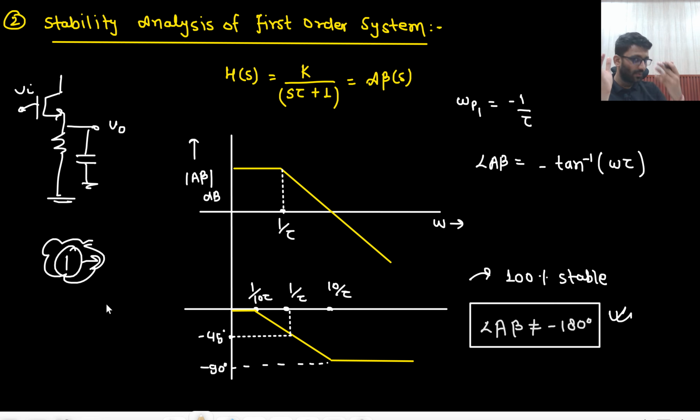So for higher gain we need to increase the stages, like 1 stage, 2 stage, 3 stage, and if you increase the stages, then phase shift will increase, and if phase shift increases, then you can go to instability. So as a designer, you need to consider how many stages you can add and how much phase shift you will get. You will draw the Bode plots, check the frequency response, draw the magnitude plot and the phase plot, and see at the frequency where I am getting minus 180 degree phase shift, what my gain is. So will it be stable or not? These are the things you need to check as a designer. It is just a simple example I am giving you.